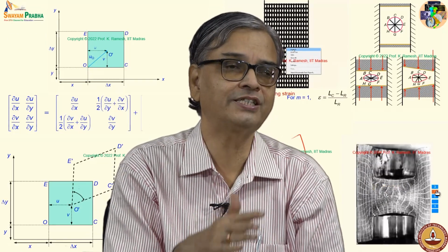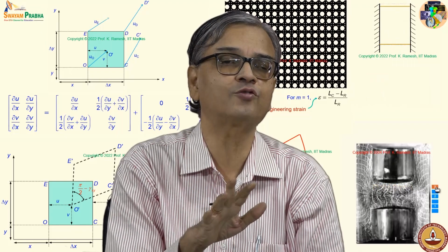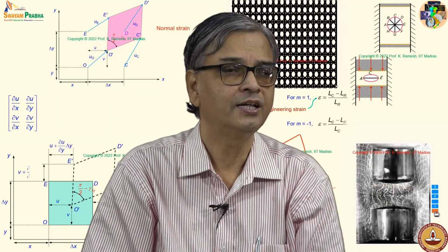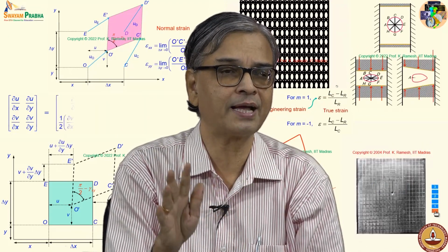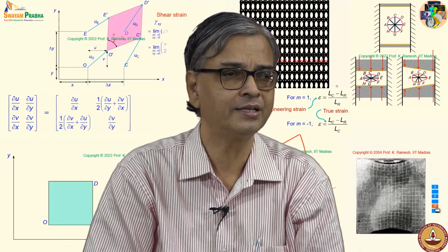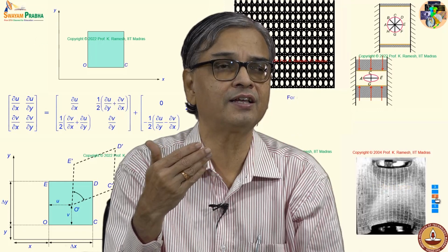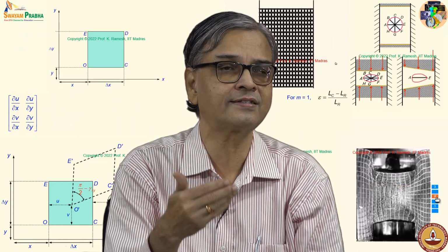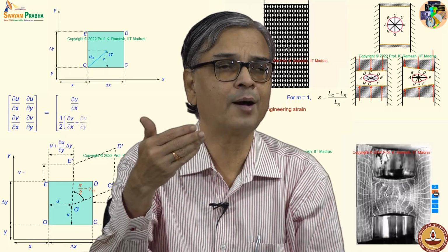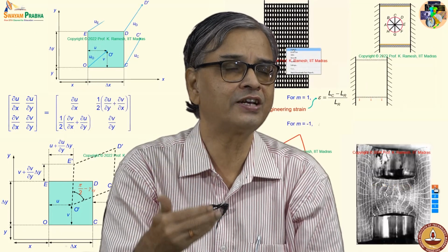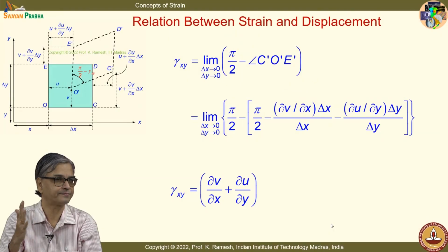Now, what we have achieved is, we have recognized there is going to be a displacement field. From the displacement field, by applying Taylor's approximation, we are now able to express the quantities like epsilon xx, epsilon yy as appropriate partial differentiation of u and v.